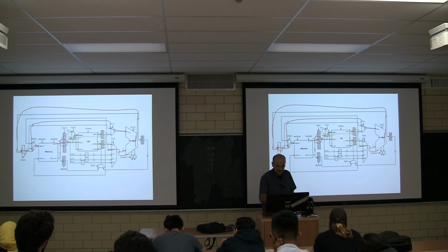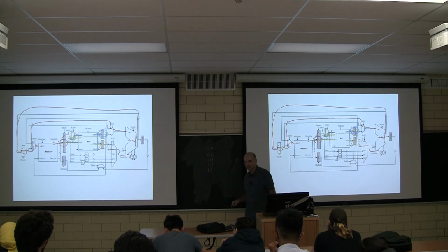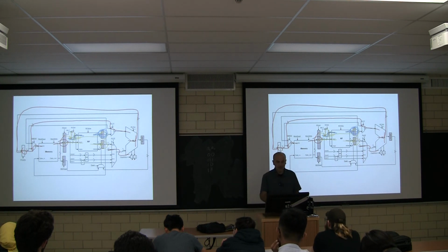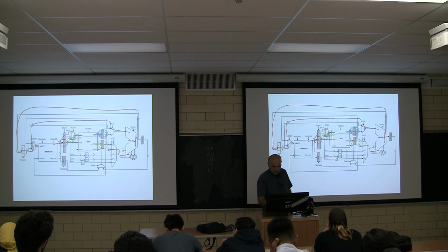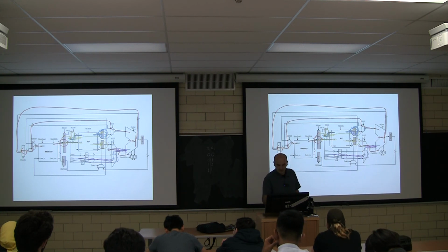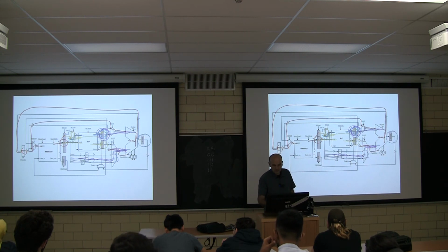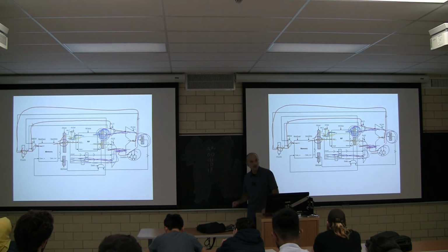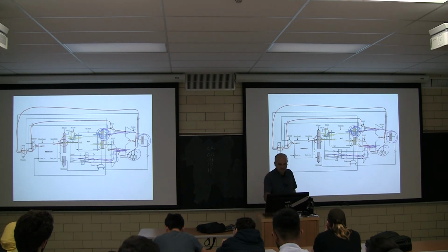Okay, can you see this? And load a new register here, value. That's cycle 3. Cycle 4, we're going to take immediate 5 as the second operand to the ALU. This R1 we read here as the other operand, and we're going to produce the result here and update the flags. We're now at cycle 4. And at the end is cycle 5.